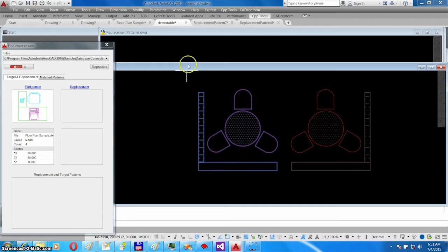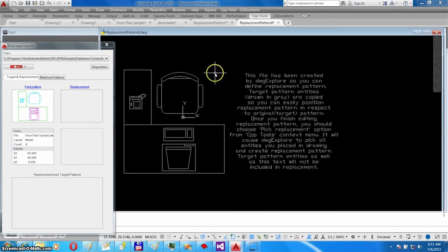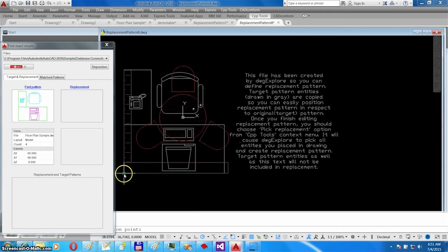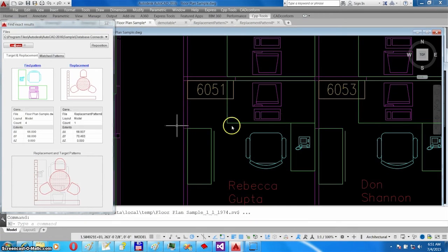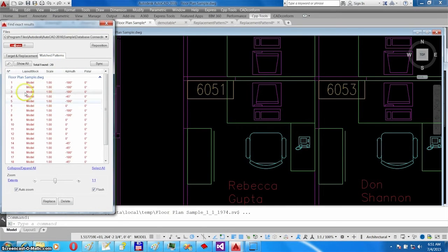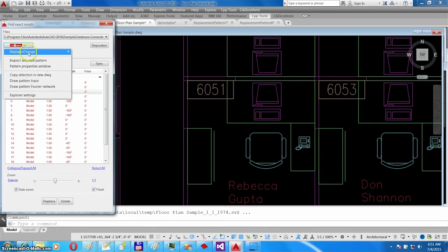Then we can switch back to Replacement Pattern Editor document and paste new content here. So there is a target pattern, a replacement pattern, and what we want is all of the matching patterns to be replaced. This time we want a true replacement, meaning that matching pattern is to be deleted and replacement pattern added. Therefore, in the Replace Change Options dialog, Replace mode should be chosen.